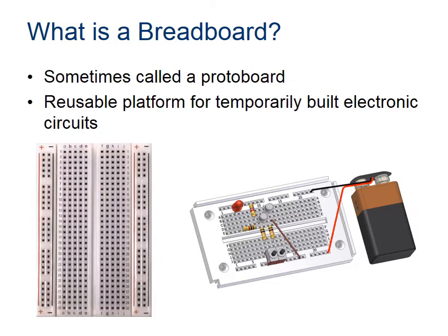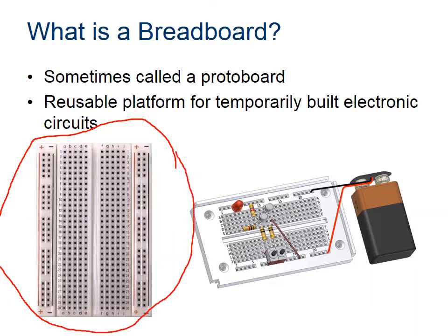So what does a breadboard look like today? Well, there are a couple of examples, and the one on the left here is an example of one that we'll be using in class. The one on the right shows you a 9-volt battery with some components hooked up. The reason we use a breadboard is it takes a lot less time and money to create a circuit as opposed to a printed circuit board. And because of the cost, printed circuit boards really should be used for a final design.